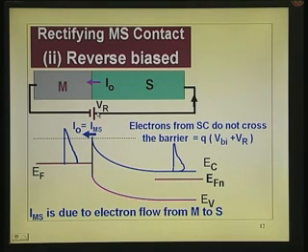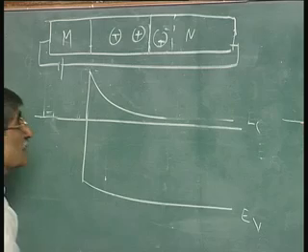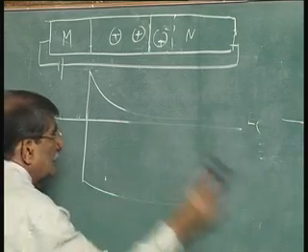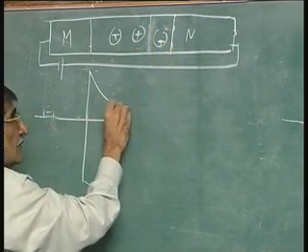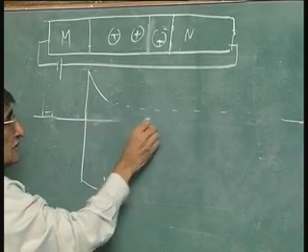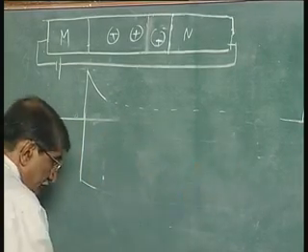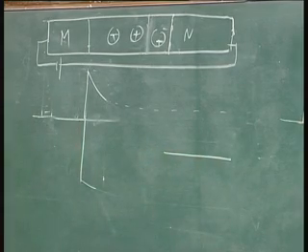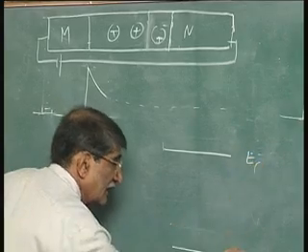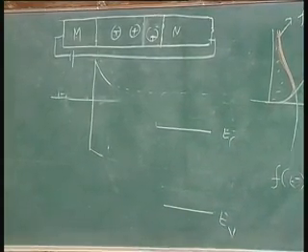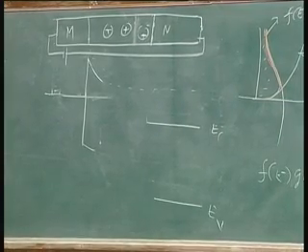Okay. What is the consequence of this? That is the diagram which I do not have to draw, you can see here. What you have to see is the neutral portion, the whole thing has come down, and this portion is slightly widened. So, when the neutral portion comes down, what happens? I have drawn it there already. Originally it was here, now it has come up to this point. So what was here originally has come down to some extent like this. I have drawn it magnified. That is, the neutral point has come down like the conduction band, and the valence band correspondingly has gone down. So EC and EV in the neutral region remain the same, the gap is the same, but only the energy has lowered because of the plus charge on the other side.